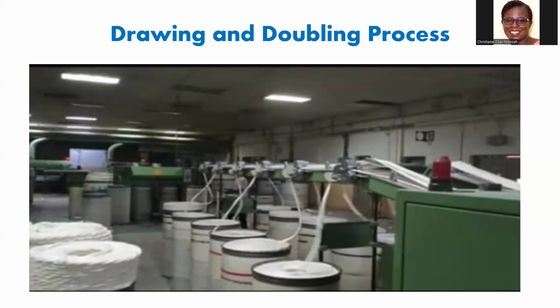But the carded sliver too, we can comb it. We can comb it to take away short fibers. So combing is an optional operation. When we need the fabric to be very fine, having a very fine surface, we do combing. Combing is taking away very short fibers, resulting in just the length, so that when you produce the fabric, it has a very fine surface. Okay. So after that, we have the combed sliver. So card sliver, then you have the combed sliver.